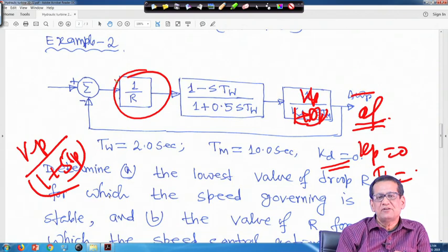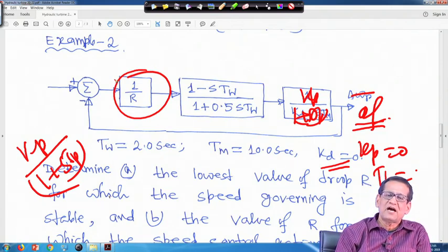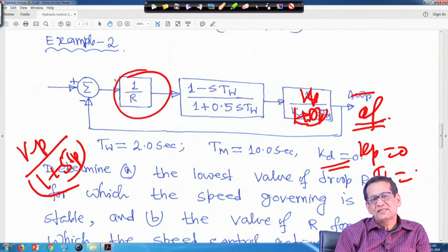And it is a very high value, right. A typical figure is 360 percent per minute for raising the generation, and for lowering the generation it is 270% per minute. It is so high that the generation rate constant GRC for a hydro turbine does not have any effect on the dynamic responses. But because of the governor time constant for a hydro turbine, it has a different time constant, larger than your steam turbine governor time constant.